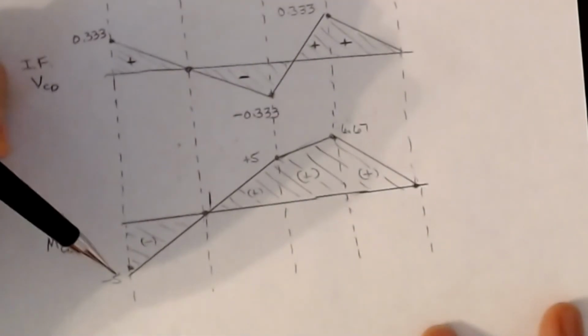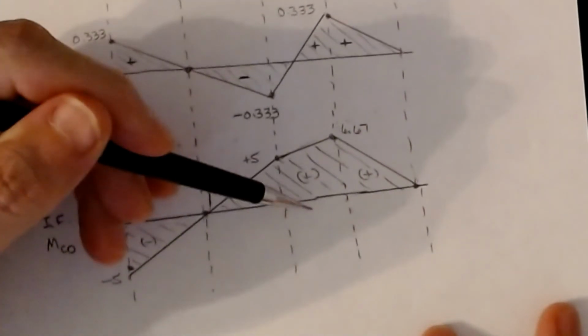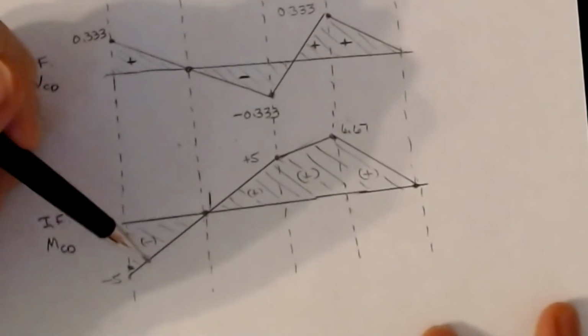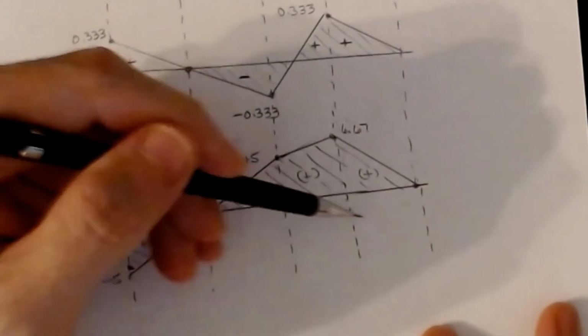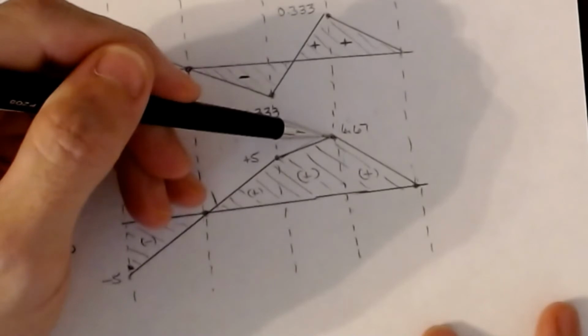This should make sense because if I put a point load out here on the end of the cantilever, I get a negative moment in the backspan. That's what I'm seeing with that negative 5 happening there. And likewise, the maximum positive moment on the span I would expect to occur somewhere within that span itself. And then again, it occurs at that x equal to 30 position as the maximum.